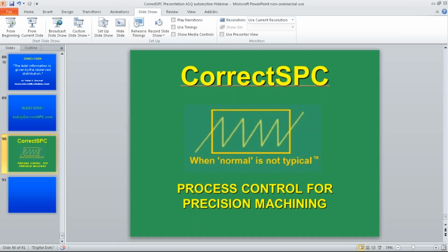I'm always looking for opportunities that might be different from precision machining where this would apply. I just haven't had an opportunity to go in, look at the data, look at the process, make sure the process is doing what we expect, and collect the data and show that it works. So it's something to consider. And if what you see is this type of thing, which is the key, the sawtooth curve, where you have a variation over time and an adjustment, because that is how you get the continuous uniform distribution, which is how this is all hinged together.